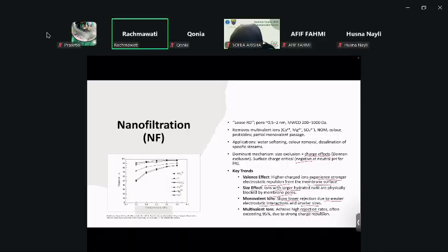And then if you see this one, this is the percent rejection, and this is the feed pressure. You can see that the top here, this is for the sulfate ion, so it's a bigger ion. You can see that the percent of rejection is quite high, meaning that the membrane rejects sulfate ion, which is good if you don't want to have sulfate ion in your drinking water. And then the next here, the calcium 2 plus, yeah, this one. And then we also have the bicarbonate ion, and then this one here is Cl minus, and this one here I think is sodium plus.